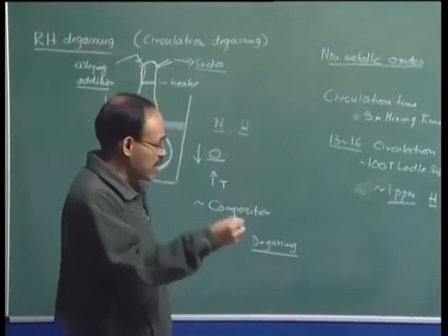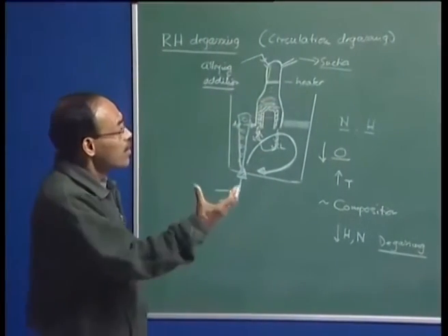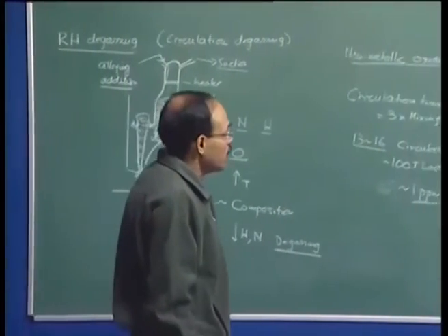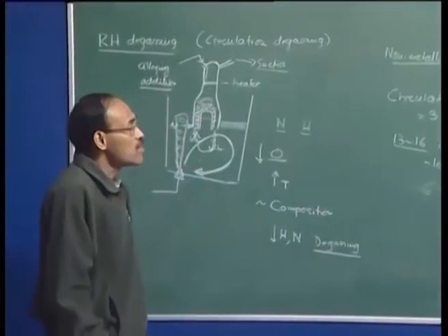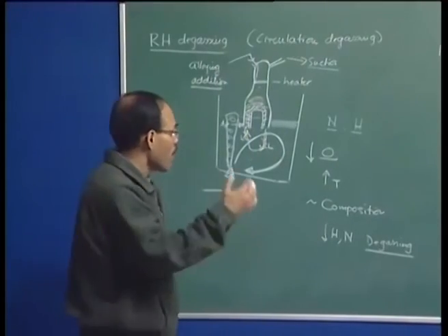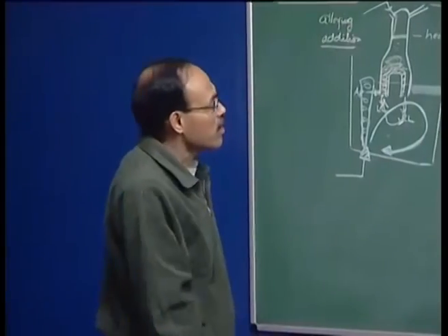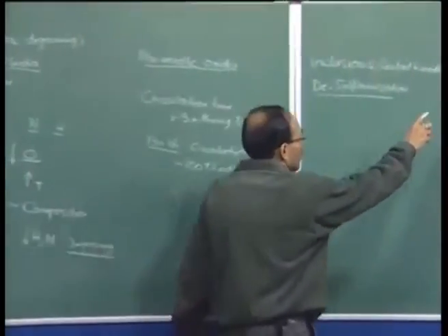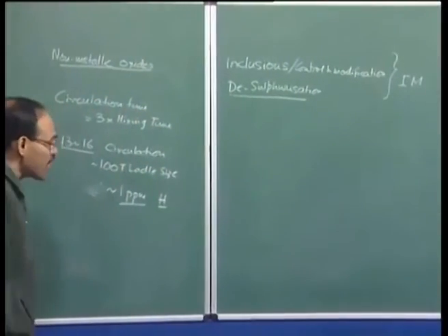Liquids have a greater tendency to coagulate or coalesce, and if they can become bigger, they can really rise up to the slag metal interface very easily. So, modifications of inclusions and desulfurization may be necessary in some processes beyond the conventional ladle metallurgy treatments, ladle furnace and vacuum degassing techniques, and there we have a host of techniques, particularly injection metallurgy, where we inject certain materials.